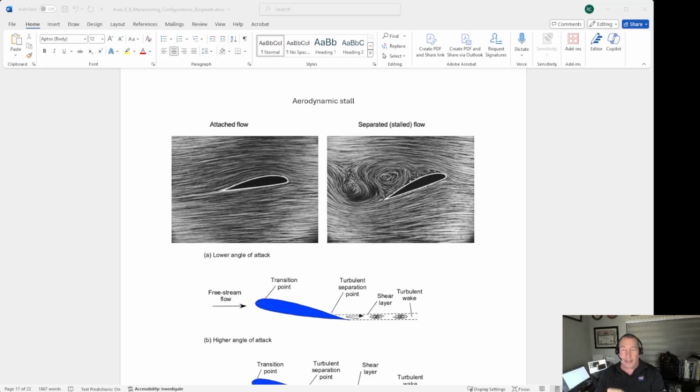In the right-hand picture, the angle gets too great and the air flowing over the top of the wing starts to swirl and delaminate, come away from the surface of the wing. This spoils the lift and causes a great deal of drag. So it goes from being beneficial to almost just like that, depending on the wing design, absolutely detrimental to lift.